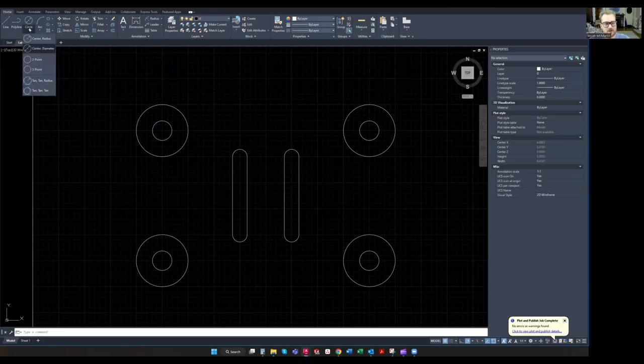And to do that, we have a tool in the circle tools. So drop down under circle tools and click this tan radius button. What we want to do here is, somewhere in the top right quadrant of this circle, click somewhere on here, and before you click, it's going to give you a little indicator that allows you to snap to a tangent line.